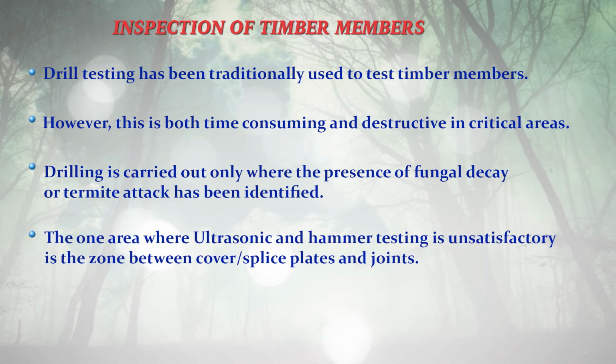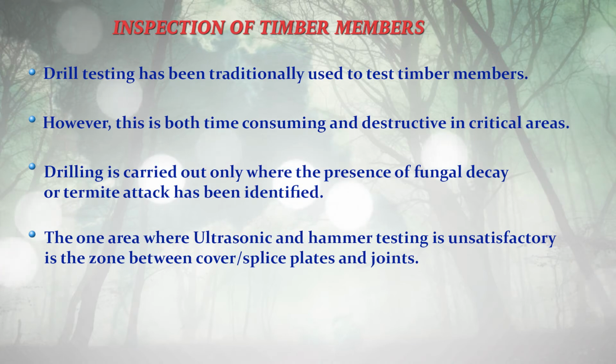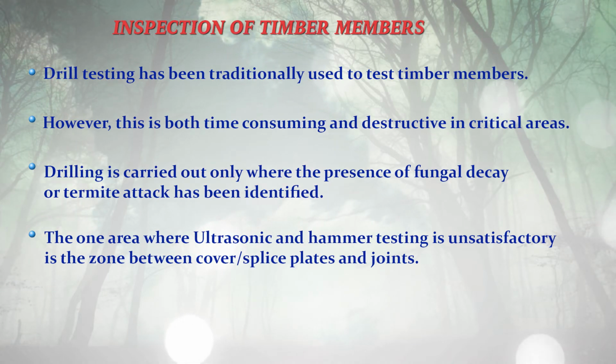The one area where ultrasonic and hammer testing is unsatisfactory is the zone between cover or splice plates and the joints. So in this zone, ultrasonic and hammer testing give unsatisfactory results.